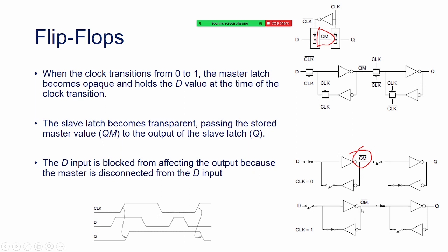Basically what I'm trying to say here is we have two latches, correct? Are we interconnecting it like this and then giving it the output, or are we connecting it like this? This is the clock. And what are these two lines you are showing? This is the Q and this is the Q bar, for a latch. Whenever you show Q, you can always show its complementary function. So if it's a Q, it will have a Q bar. A flip flop will always have complementary outputs.